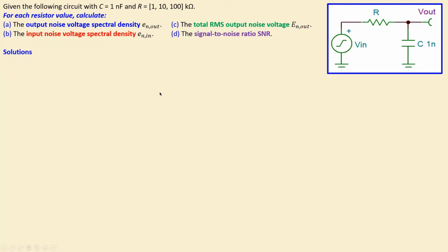So how do we work this out? Of course, we will begin with the model, and for that we need to disable the independent source. In this case we just have one, the voltage source. We know from circuit analysis that an independent voltage source will be a short, and a current source will be an open. So I will short it out. That's actually what I have.